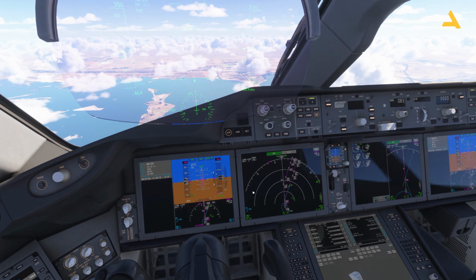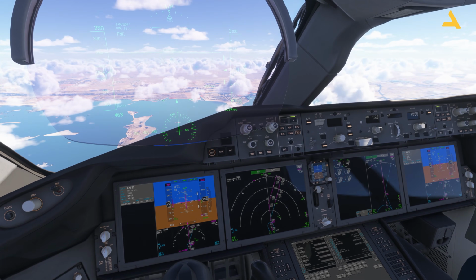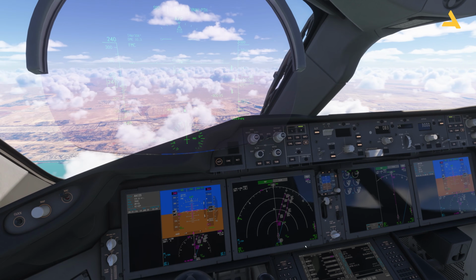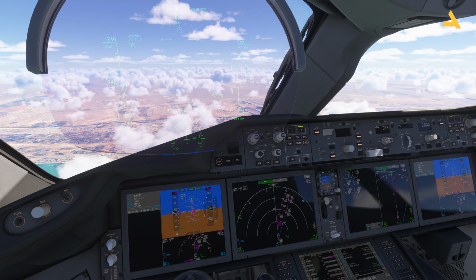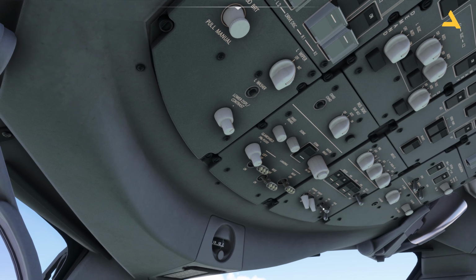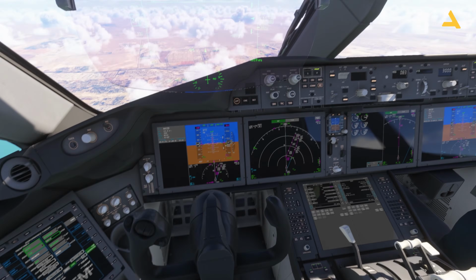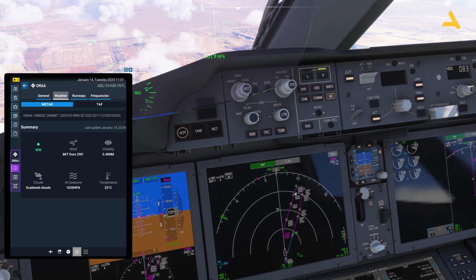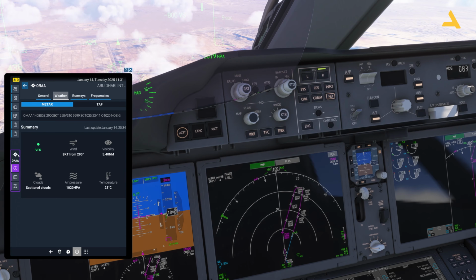And below 10,000 feet, you also have to turn on all the lights for the landing. Now this was the chime for the seatbelt signs, and the seatbelt signs are set to auto. Now I can also turn on the lights for the landing, and that's it. Now I will just wait for this point, because let me just bring up the chart.